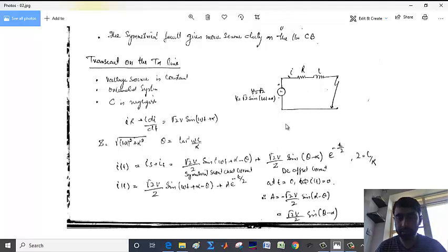If you remember, if we write it in terms of phasors, it will be simply V, the RMS value, divided by Z at an angle of alpha minus theta, because this current will be lagging the voltage by an impedance angle theta, that is tan inverse omega L by R. That is why we have introduced minus theta over here, and the current magnitude will be simply V by Z, that is root 2 V by Z, the rest is the same.